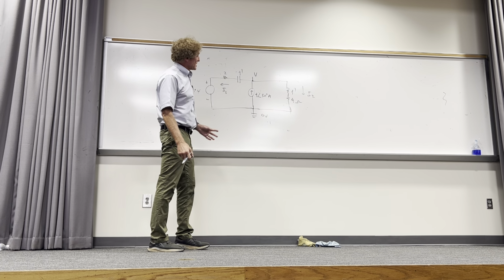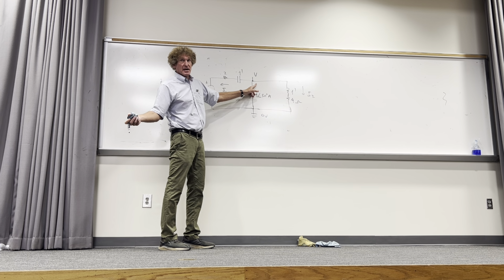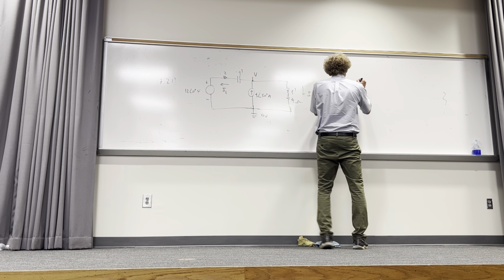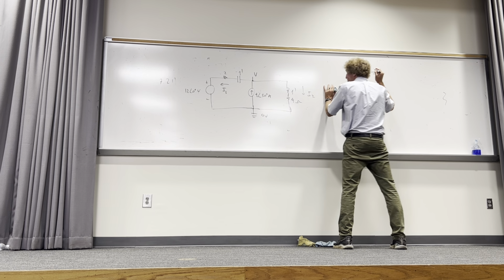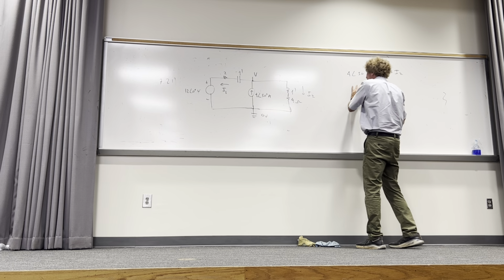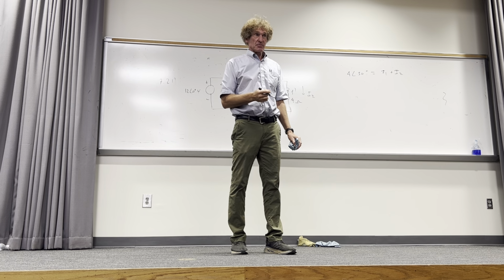What I'm going to do is say all the currents into this node, this would be the only node, do you all agree with that, class, equal all the currents out. If I look here, I have 4∠30° going in, and what's coming out? Well, I1 and I2. I'm trying to be clear about this. I don't want to hurry up. I think we can all see the logic on this, right?